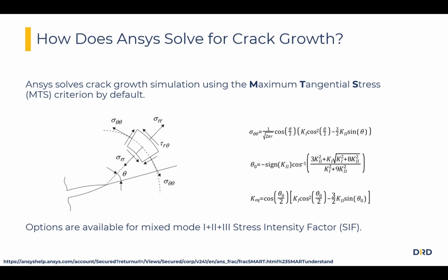And then, of course, Ansys will calculate the stress intensity factor from the far field stresses and the angle at which the crack grows. We can have general 3D crack growth, so we can have mixed mode loading that will lead to mixed mode crack growth. So the crack can grow off plane at an angle and so forth.